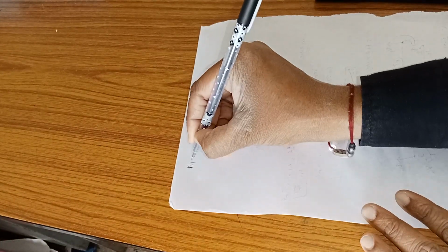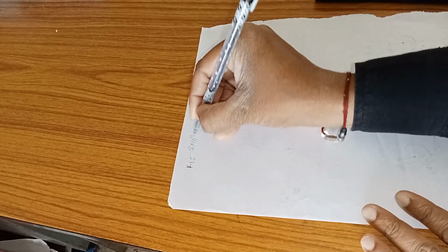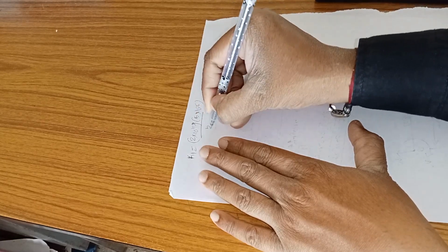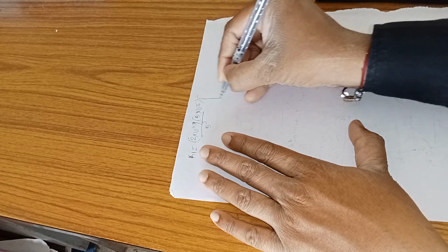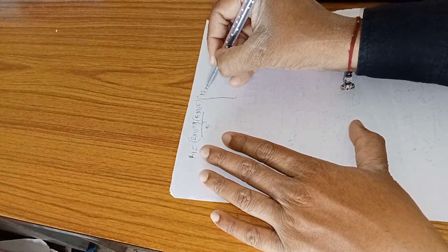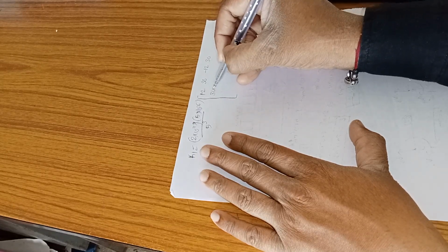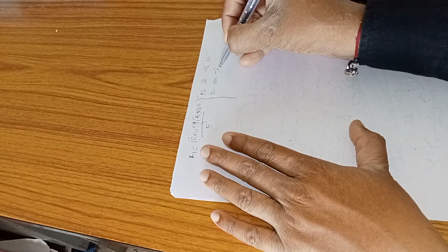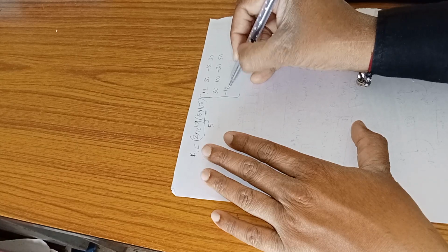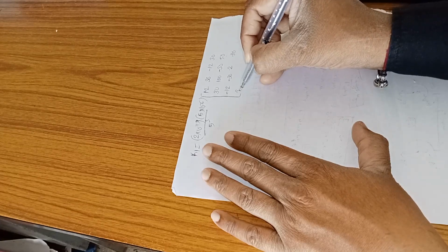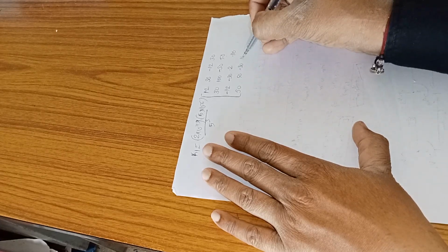So upon substitution, let me put K1. K1 is nothing but 2 into 10 to the power of 11, that is E, and I is 5 into 10 to the power of minus 6, divided by LE cube, that is 5 cube. Once I substitute, I'm going to get the answers as 12, 30, minus 12, 30. That is, I'm going to substitute the values of L. So 30, 100 and minus 30, 50. You can just put it in your calculator and get the answers. And here it's going to be 30, 50, minus 30 and 100. So it is just going to be like that. You can check it out here as well.